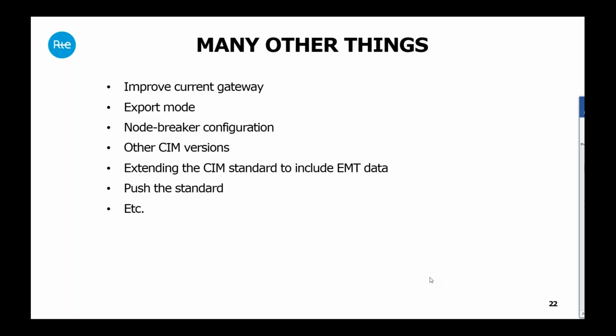Sometimes the issue becomes more and more complex for high frequency transients. In the case of an AC line segment in CIM, we can add additional data like the representation of towers, insulators, grounding impedance, etc. We also have a surge arrester model implemented in any EMT tool, but there is no CIM equivalent to surge arrester to date. So this gives an insight into the complexity of converting EMT data to CIM format.